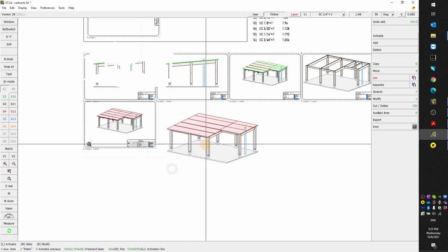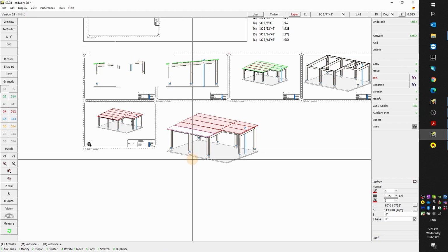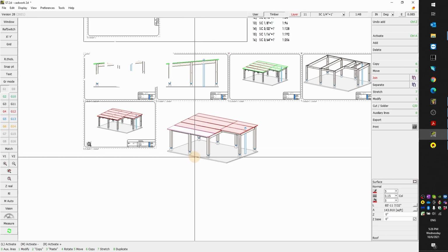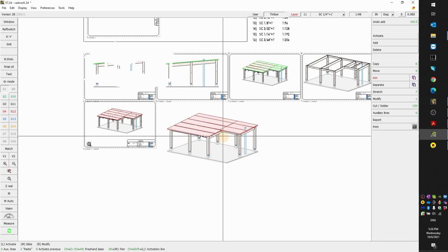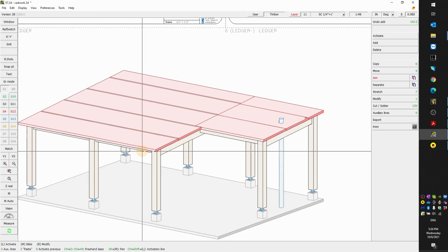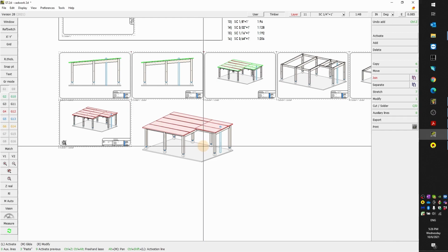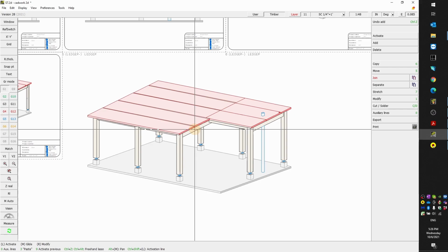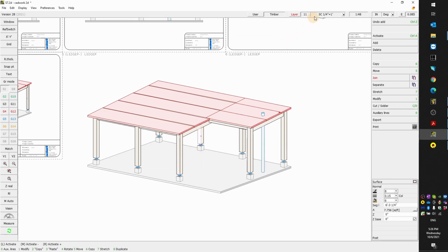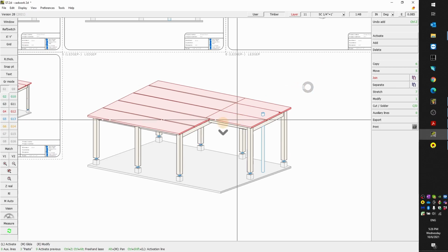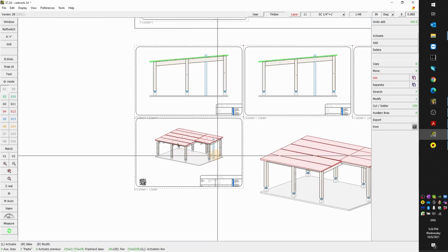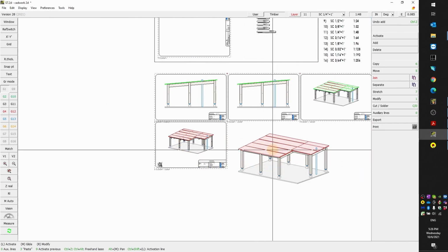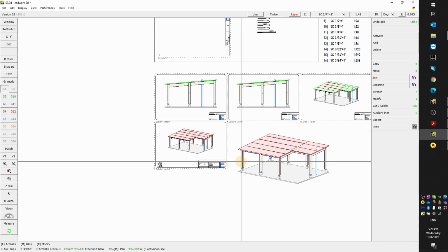So you see there are no frames. Sometimes you have a large format like a D size or E size, 24 by 36. You want to bring a drawing at a certain scale so you can place multiple drawings on a large format paper. So that's also feasible. Now you see if I click on this, this is indeed at a quarter of an inch equals a foot. So that's the main difference. But otherwise you see that the representation of the model is exactly the same, whether you use colon or semicolon.